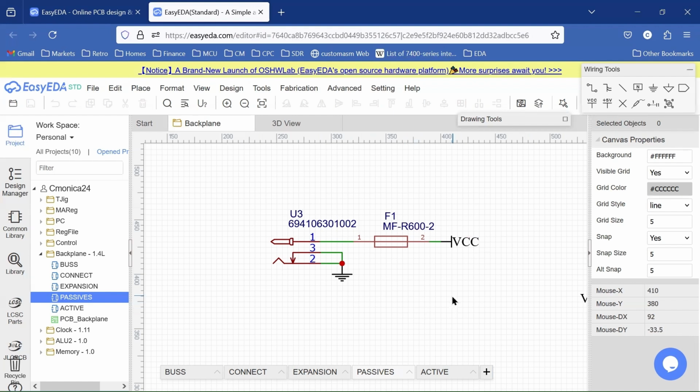But what happens is, we have a lot of capacitors in our circuit on all the different boards. And when the power supply is initially applied, those capacitors are effectively a short to ground. So when you apply the power, the current draw goes very high, right?